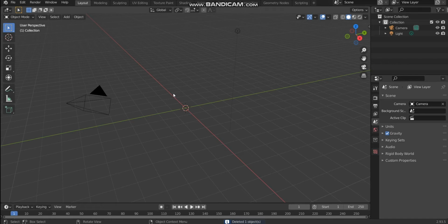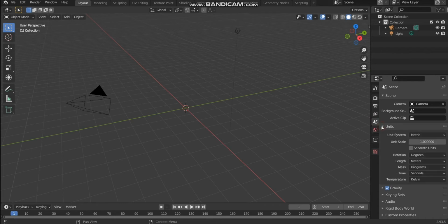So one thing that I'd like to note is that Blender doesn't really care about units, so we'll disable the units that we have in our scene. To do that, simply go to Scene Properties, and then go to Units, and set the unit system to None. The reason we do this is to make sure that when we're exporting our 3D model, we all have the same scaling factor. Awesome!